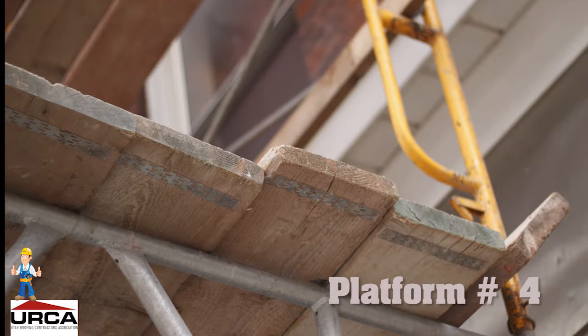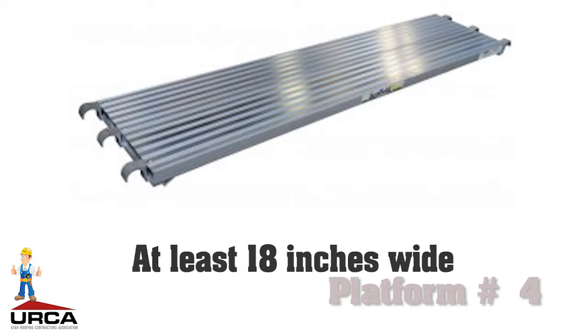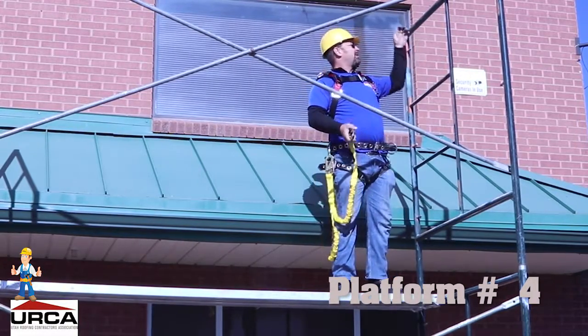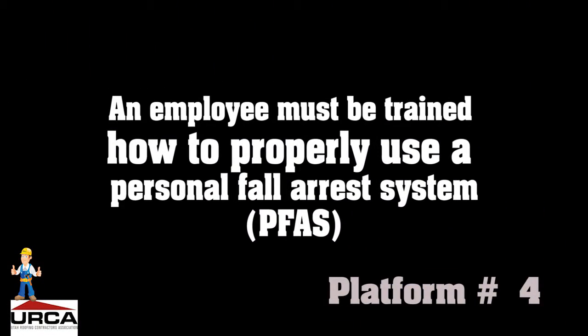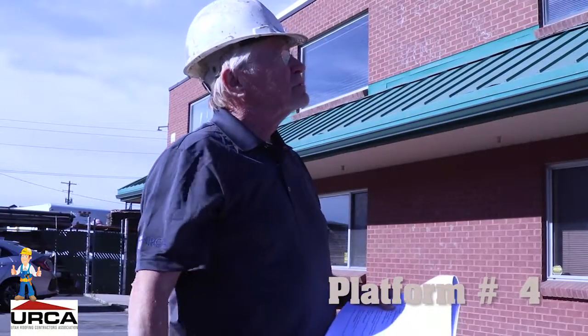There should be no gaps between the adjacent planks or deck platform units greater than 1 inch, or between the platform and the uprights. Each end of the platform must extend over its support by at least 6 inches. Platforms and walkways must be at least 18 inches wide. If less than 18 inches, a personal fall arrest system is used to arrest a worker's fall. An employee must be trained how to properly use a personal fall arrest system. Workers should always wear hard hats on a platform or while around a scaffold.